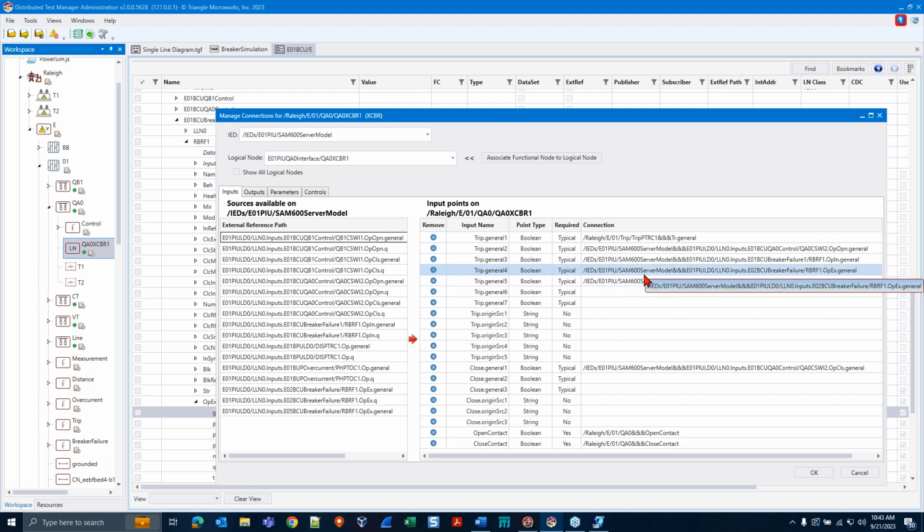So I didn't have to do this mapping manually because the information needed to do this was contained within the SCD in really 2 different ways. So first and most importantly, it's contained within the substation section. So that defines sources, or it contains source refs as part of the 6-100 extension that's currently being worked on within the working group. And it contains what inputs are necessary for a given LNode to function. Now, crucially, once we moved into the implementation stage, that source ref included a link to an XREF that actually implemented or realized that signal.